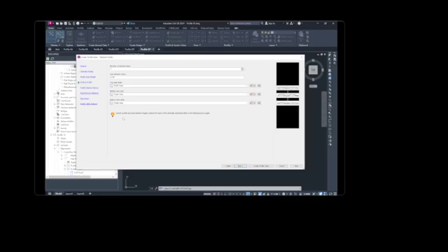and once there, we're gonna specify number of stacked views to 3. Gap between views is 0. Top view style, stacked top. Middle view, stacked middle. Bottom view, stacked bottom. Click next.